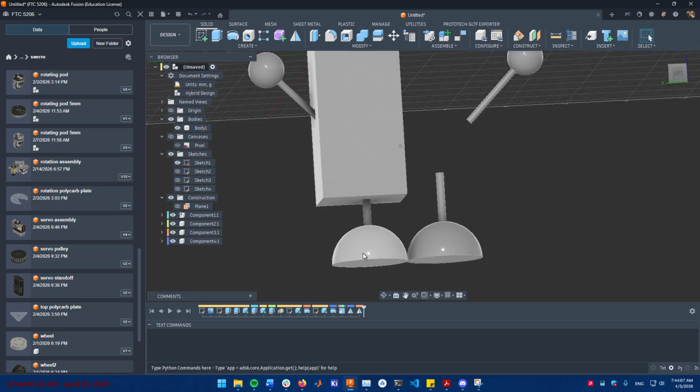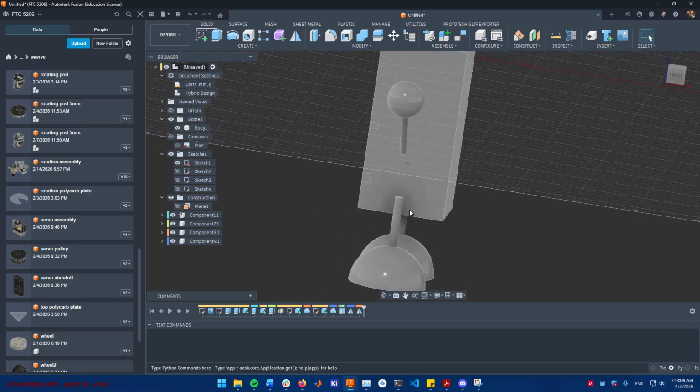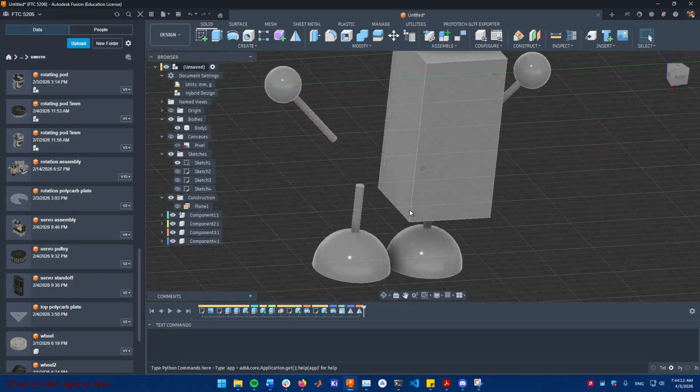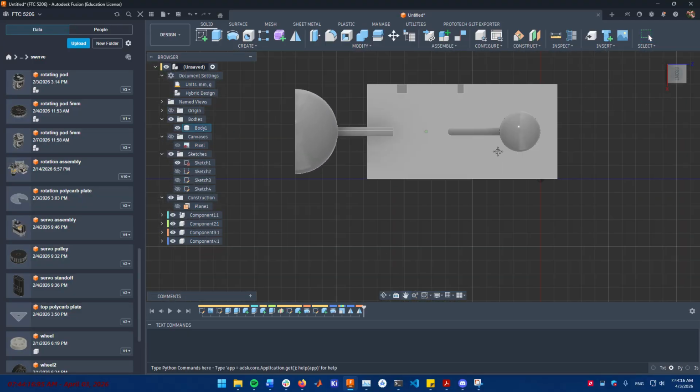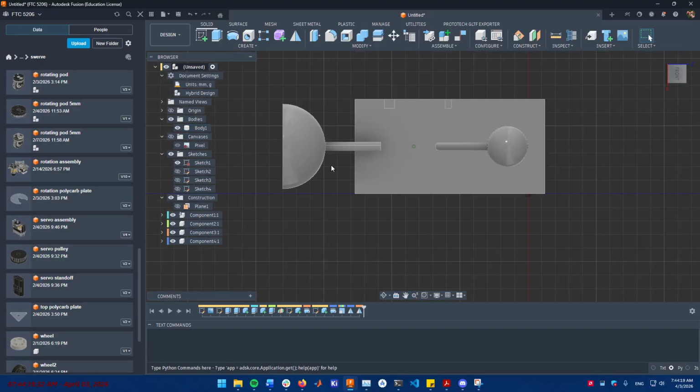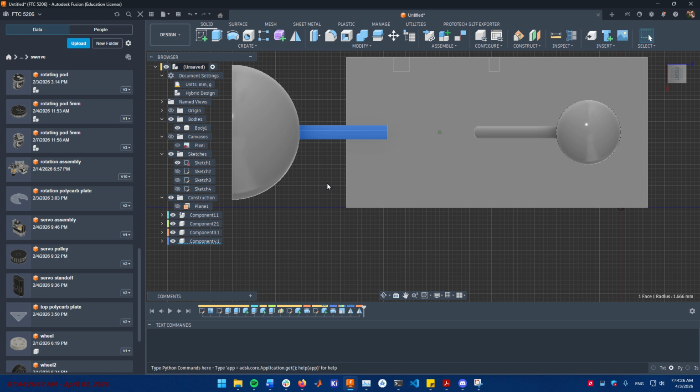this is very hard to print, since what orientation are you going to print it in? You can either print it on the back, but notice what we have here, right? If you lay it on its back, then this joint will be very weak because it goes against the grain, or like the extrusion path of the print head. And also you have to have a ton of material down here. If you can see where my mouse is, you have to have all this material down here, and also this will look very ugly.